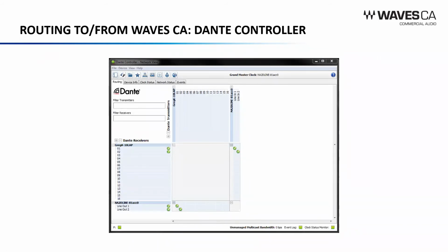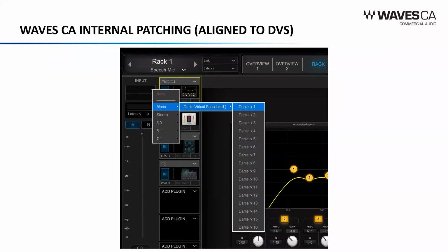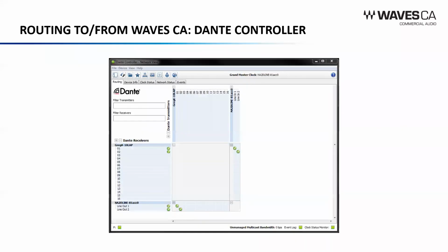to and from. So between the two screens, you would have your Dante controller, which you may be running either natively as the Dante controller in your network, or perhaps you have it implemented as another controller on your installation. And you would then set up each stream into the CA on the particular stream that you would like to use. So these two work together so that you have exactly the audio stream you want coming to exactly the preset that you select.